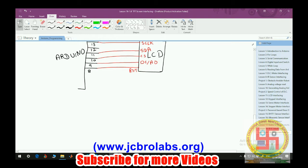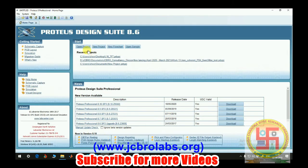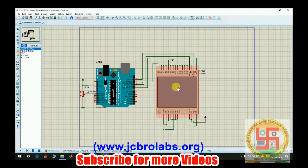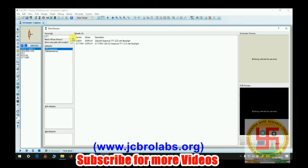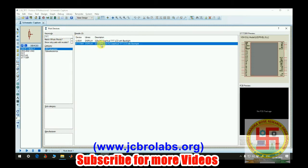So you have seen our hardware circuit. Now let's have a look. Prior to burning the program on hardware, we have created a model on Proteus as well. So let's have a look at the model on Proteus. Here we have created a model on Proteus. This TFT LCD you can find by the name of Simple TFT. So you will get the ST7735 TFT here.